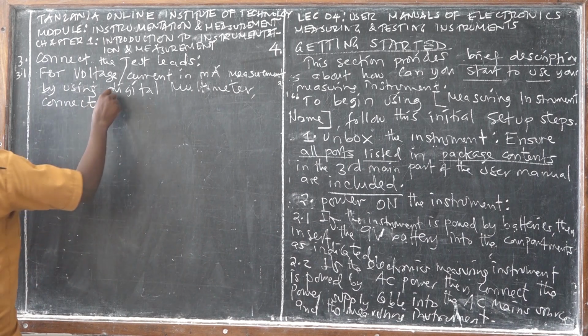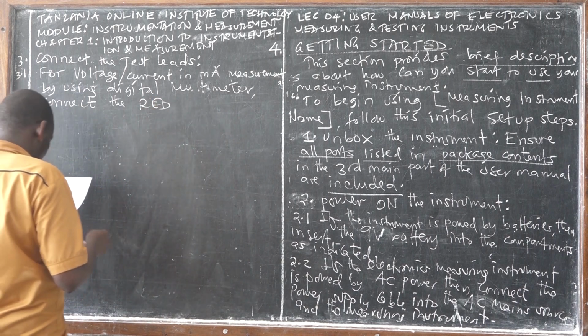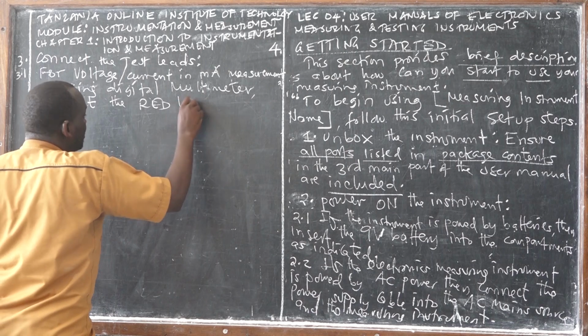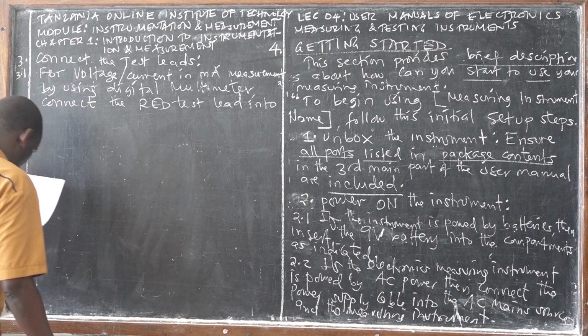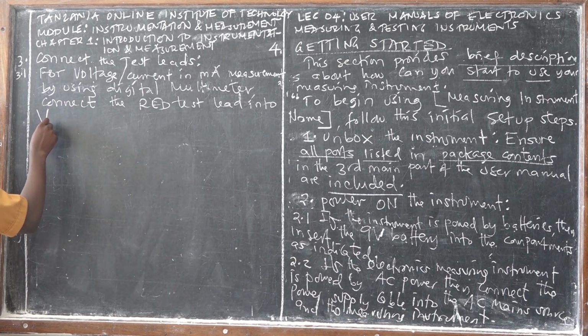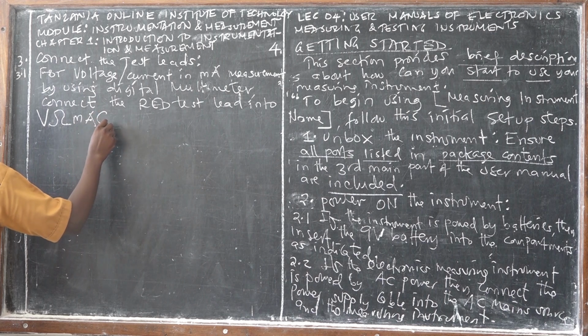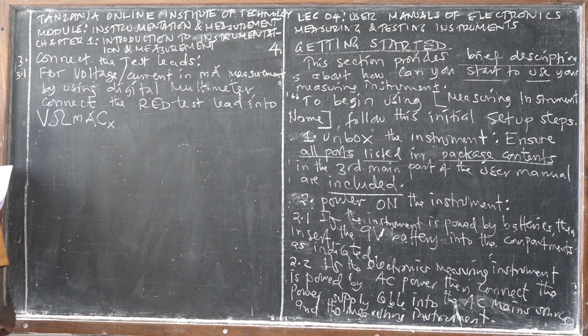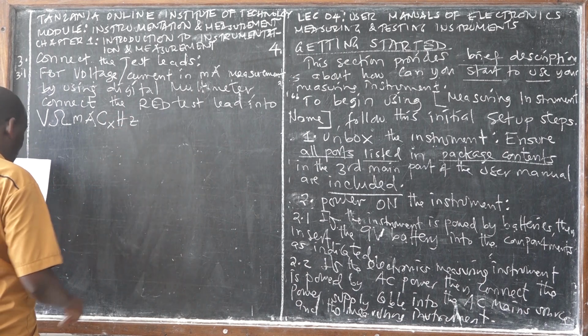So connect the ready test lead into the voltmeter or ohmmeter, milliampere, capacitance, frequency terminal.